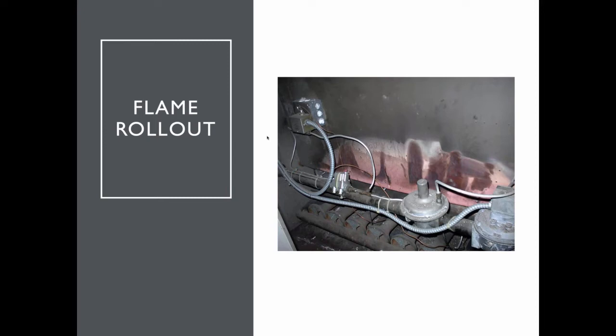Anytime it changes, carbon monoxide likes to spike and elevate. So when you're pulling the flue gases out backwards like it is, you're going to have really high CO. And this is things that have to be looked at, and you need to document this when you're on a job site.